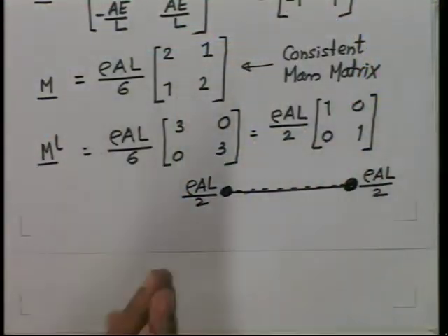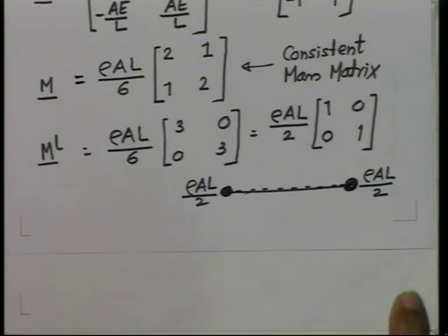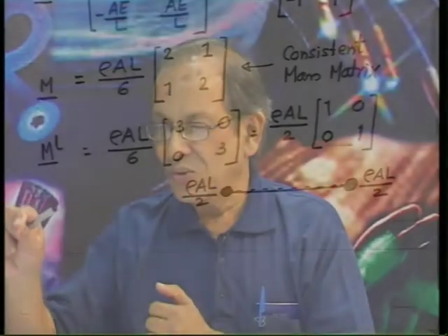So, otherwise, this row sum method is a very simple method, but later on it was formalized, because when people saw that diagonalization helps, they said, supposing there are degrees of freedom. Now, when we go to beams, you will find that the nodal degrees of freedom will be displacement as well as rotation. So, there will be one displacement, one rotation, one displacement, one rotation for a two noded beam element.